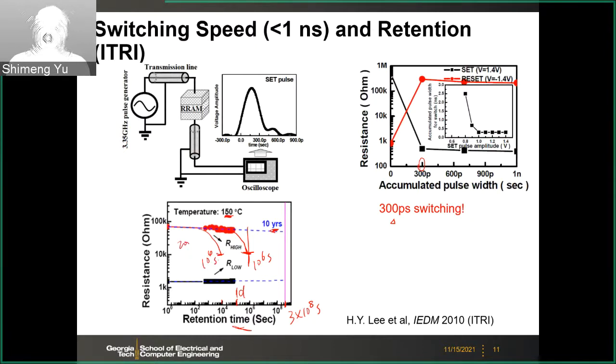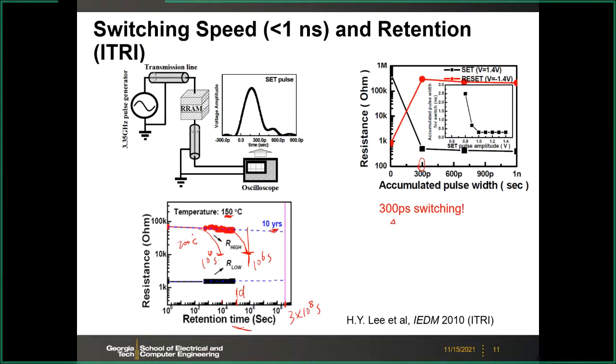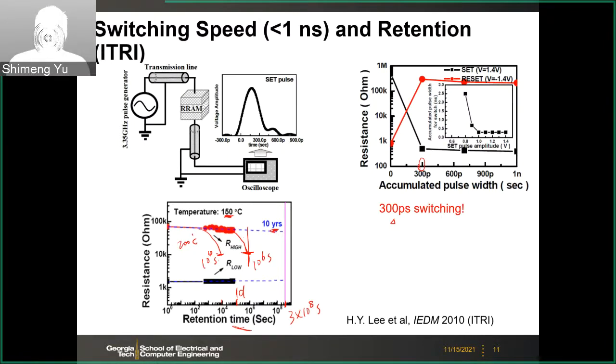With those points, you of course vary the temperature in more steps, so you can get a few more points in the 1/kT plot, and then you do a linear fitting to extrapolate to lower temperature and for 10 years, as you have done in homework.